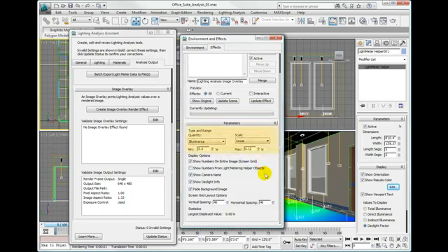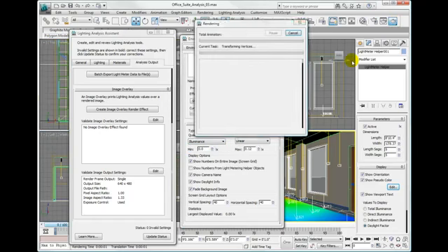Under the Type and Range, we have the quantity, meaning whether it's illuminance or luminance, and the scale, whether it's linear or logarithmic. Well, we're going to measure the luminance. However, notice that we do not have the ability to measure the daylight factor as an overlay. This daylight factor is just available in the light meter within the viewport as a measurement. So we'll keep illuminance. We'll go ahead and hit the Render button from the main toolbar. Click Render.